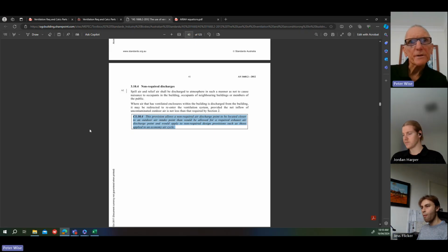So when you're doing the inputs for the calculations, there's a tab there that'll ask you if there are any preconditioners. A preconditioner is an ERV, basically. If you're preconditioning the outside air, Camel needs to know that, because if you ignore that or say no, there aren't any, then Camel assumes that the outside air coming into the space is at ambient conditions, so temperature and humidity of the ambient air.